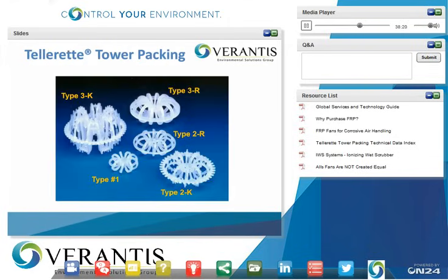The style of filamentous packing that Verantis offers is the Telluride tower packing. This actually is the original filamentous packing that was developed back in the 1960s. That would be the type number 1, the small spiral, shown towards the middle left there. And then at the same time, over the years, we have a number of different styles that we have designed and developed, again, trying to improve this concept of reduced pressure drop and higher efficiency at the same time. And that's what our K series represents, the 2K and 3K packings.